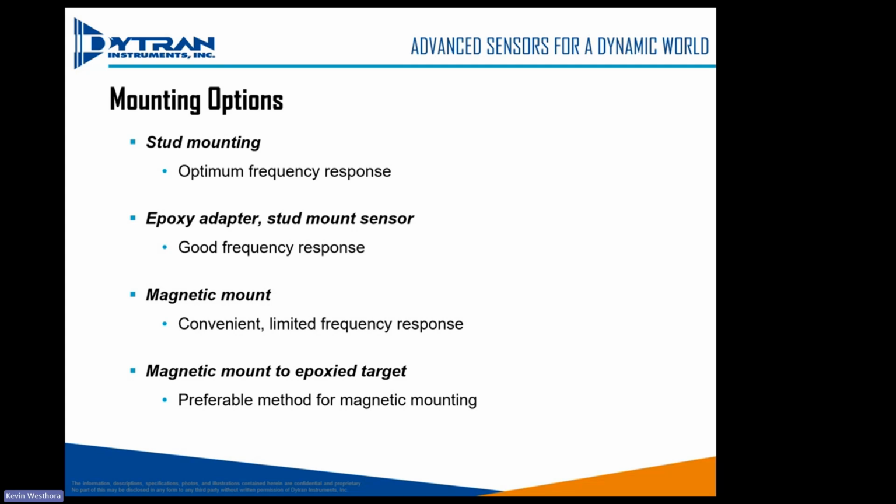We do have some customers that like to use magnets. We offer many different types of magnets at Dytran. Most people either stud mount it or glue it, but in some applications, you are not able to drill and tap into your test article. If you're trying to test a cell phone, you're not going to drill and tap and mount an accelerometer. You're going to glue it. Excuse me.